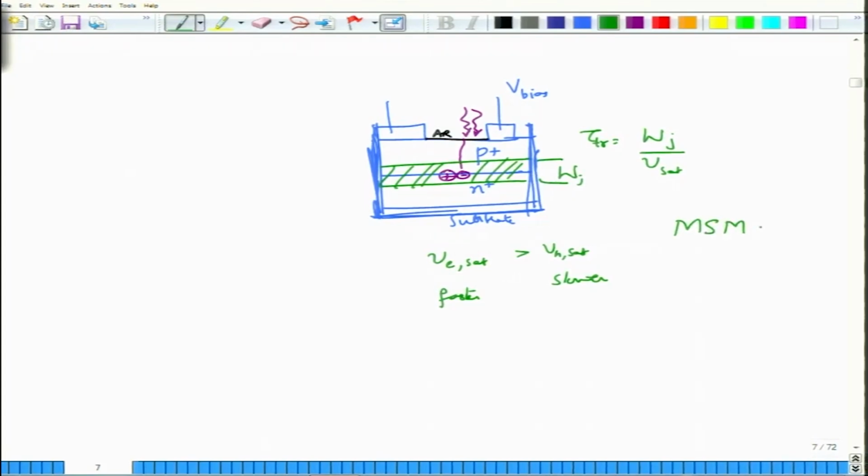They are called metal semiconductor metal photodiodes, okay, where the metal semiconductor and semiconductor metal junctions act like the Schottky junctions, which have only majority carriers. Usually this S is the N type semiconductor, and this is also possible. They also give you very high photocurrent for a given optical input, and they give reasonably large bandwidth as well. But let us get back to this semiconductor based thing.